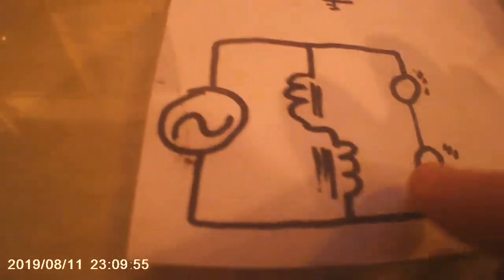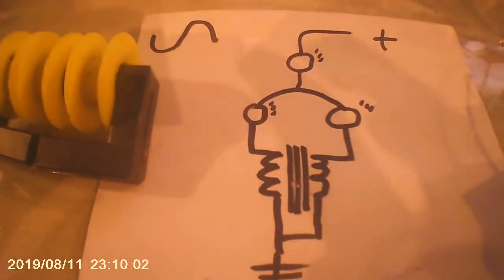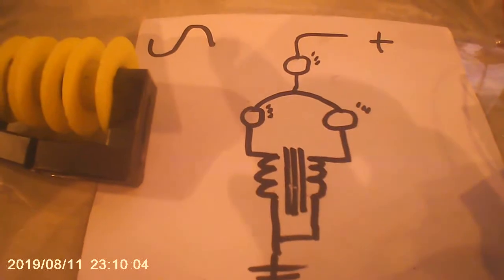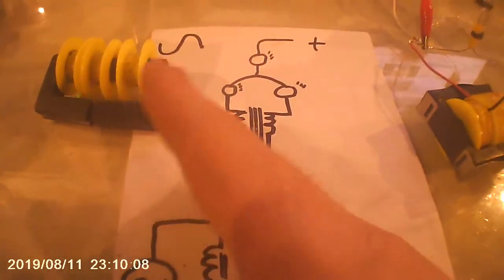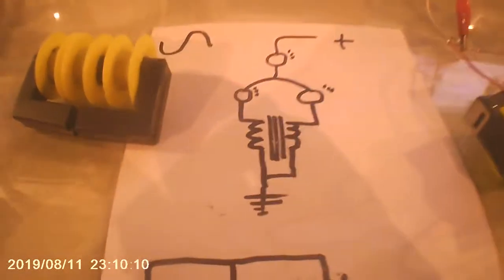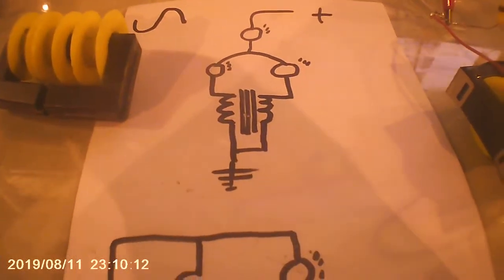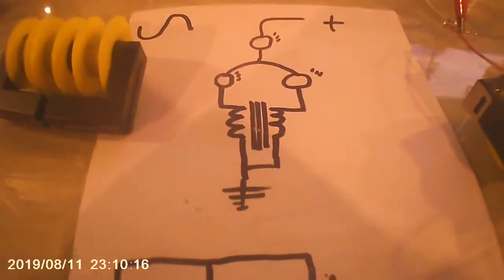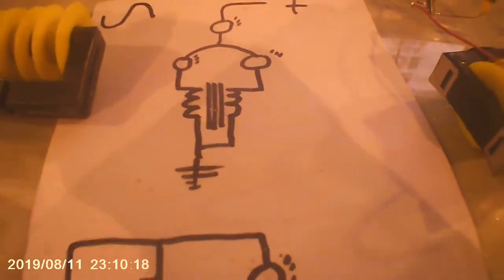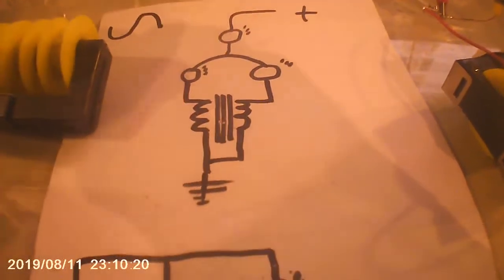Basically, I think what was happening is the extra energy from this circuit here actually was backfeeding the power supply, and although the power supply was set for 15 or 20 volts, the needle just went straight up, and my scope wasn't reading it properly. My scope was jumping around all over the shop, and basically it blew the power supply.